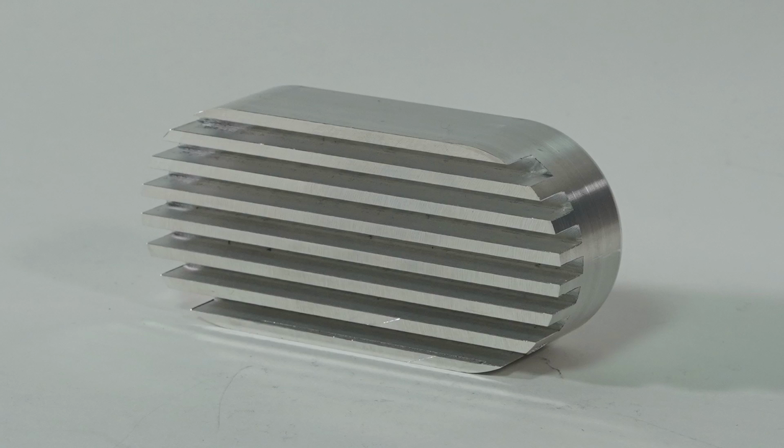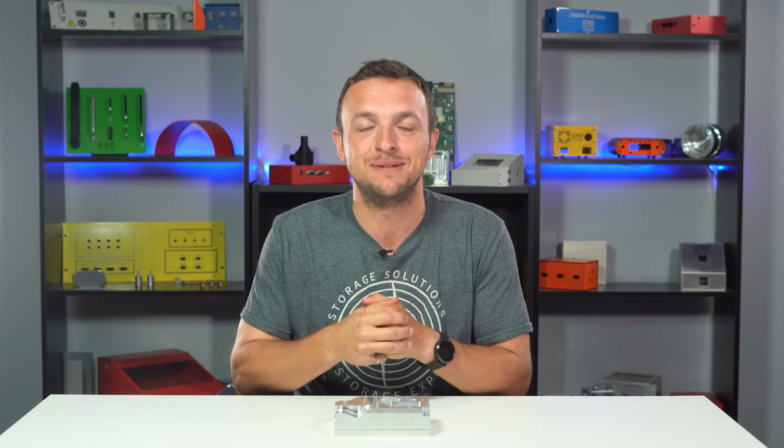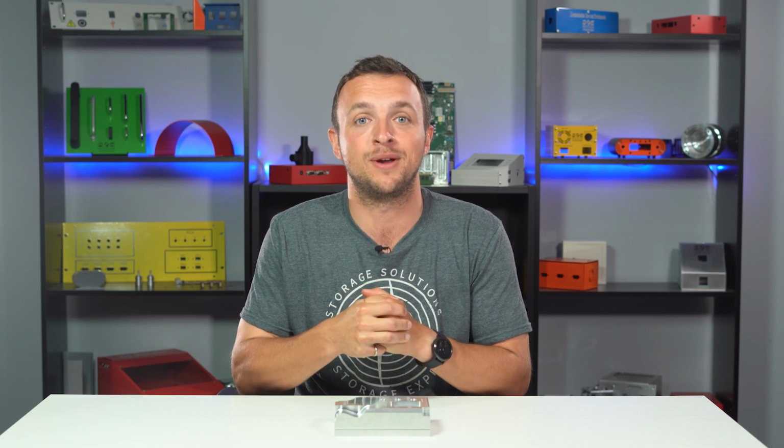The reason we differentiate between pockets and grooves is because we need to use a different machining strategy to create both. Grooves are often a lot more time-consuming to manufacture as their deep, narrow geometry prevents chip evacuation, which can increase the risk for tool breakage.